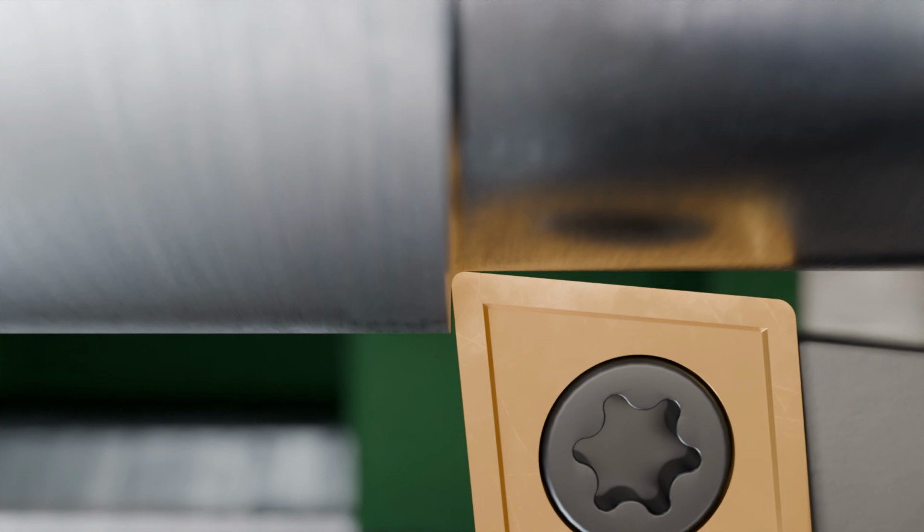Paradoxically, the depth of cut has only a minor influence on the tool life. Although the absolute load on the cutting edge increases with increasing depth of cut, the length of the cutting edge engaged in the cut also increases proportionally, so the load per millimeter of cutting edge remains almost constant. Therefore, large depths of cut allow for economical machining of turned parts. Additionally, fewer individual machining steps are required, which positively affects the tool's overall usage time.